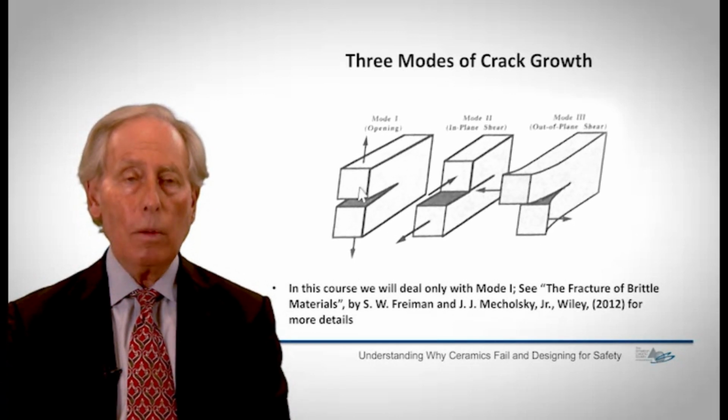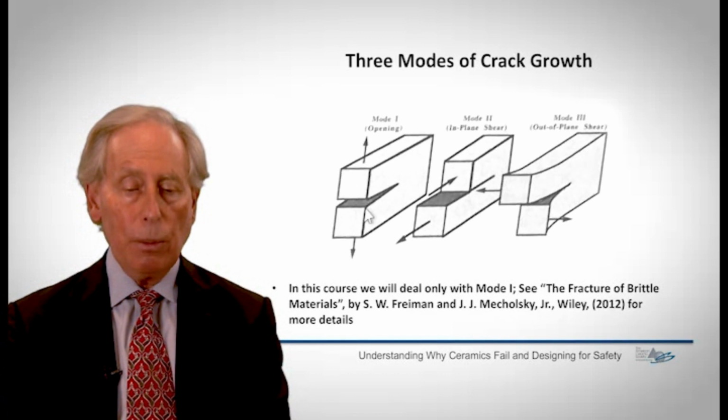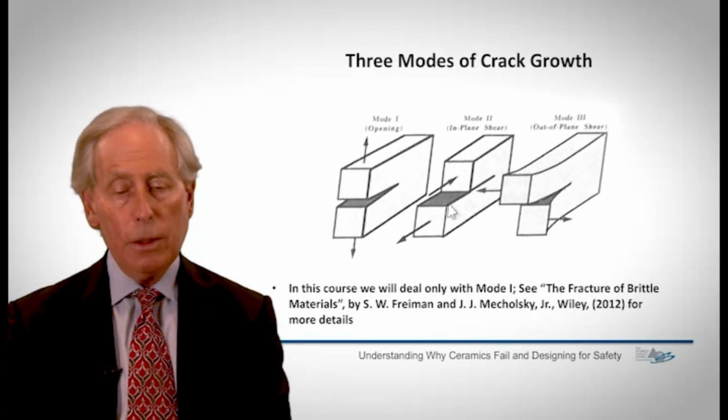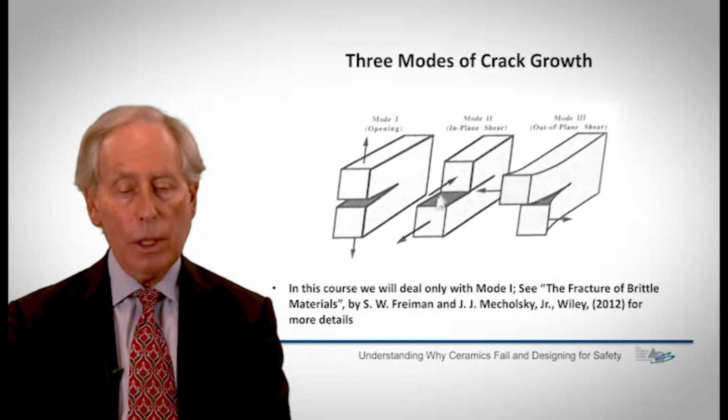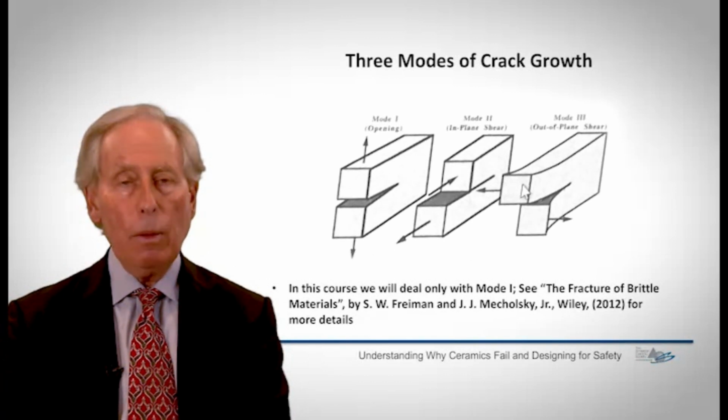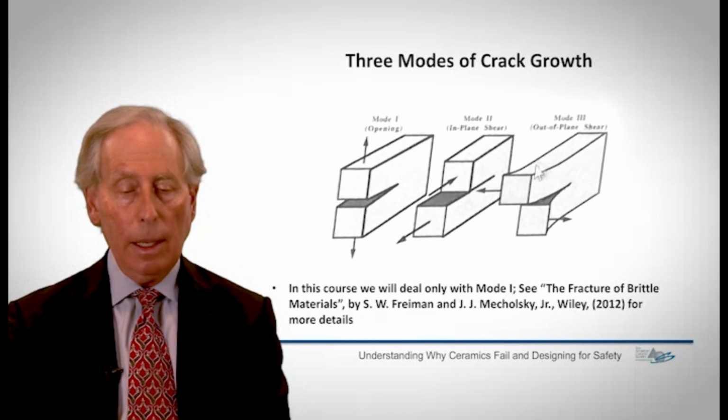The opening mode, which we're probably most familiar with, we simply pull on this and the crack moves in this direction. This is called mode 1. In mode 2, there's what we call in-plane shear, and you can see what happens. There's a shear stress applied, and this grows the crack in the same way. Or there's what we call mode 3, which is out-of-plane shear, and you can see the crack growing in this way. In this series of lectures, I'm going to only talk to you about mode 1.